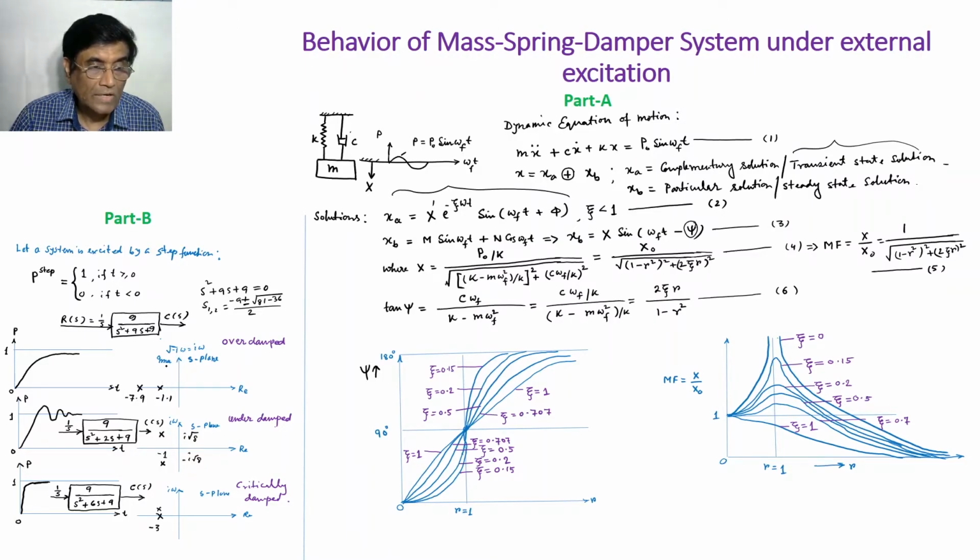We can plot the roots of the second order system, which we call poles in control terminology. The roots are here, and since the solution has e to the power minus something plus e to the power minus something, there will be no oscillations; only asymptotically, exponentially, they will reach towards 1.